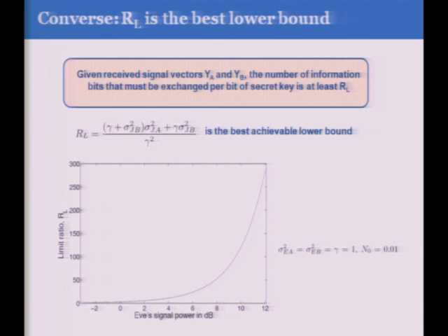So this is the plot of that. In these terms, I should have expanded this out. There's an alpha squared term, which is the interference power of Eve. Each of these terms has some alpha squared in there, and this gamma is the variance between A and B. These are slightly involved terms which have alpha squared in them.